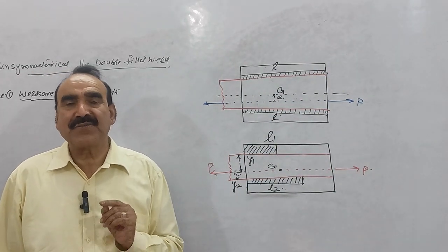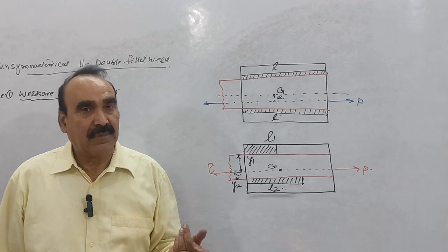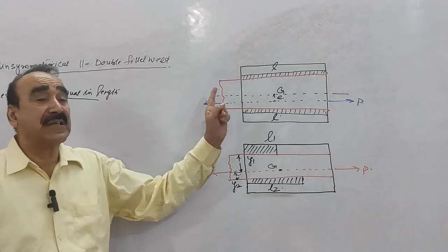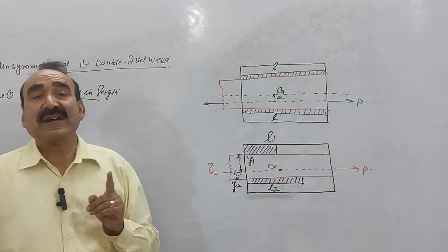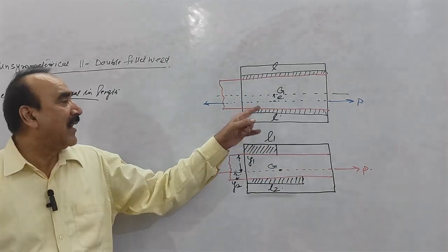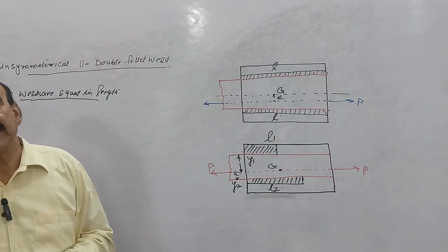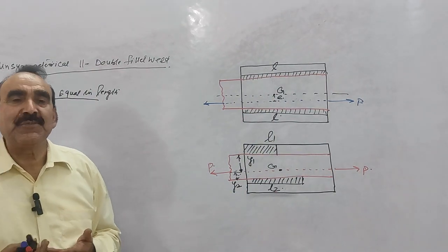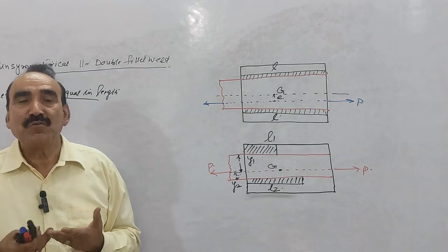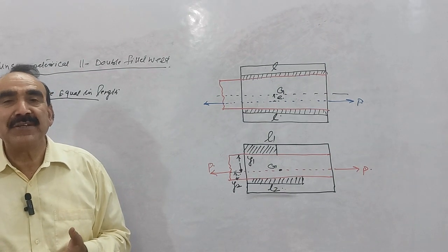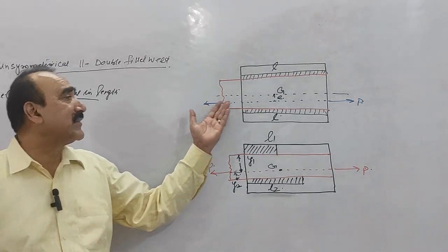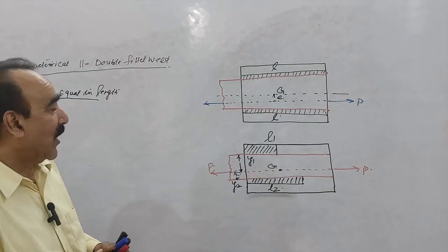That is the reason. For this purpose we have to adjust all the things. Means the force is not passing through the centroid, the force is passing at some distance from the centroid or at some distance from the bottom, you can say, right? So when the force is passing at some distance, what happens? क्या होगा? The movement will develop, और movement जब develop होगा क्या होगा? वहां पे stress produce होगी, stress और add होगी, because already we are getting the stress due to this P. तो stress जो है और produce होगी.